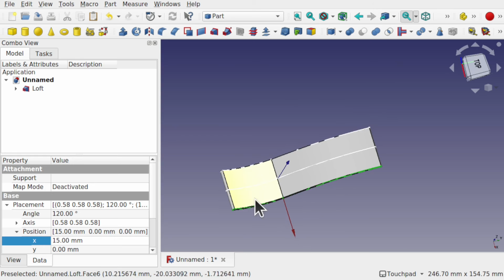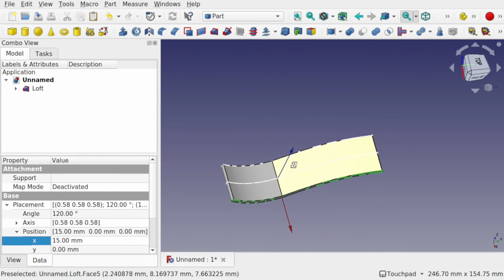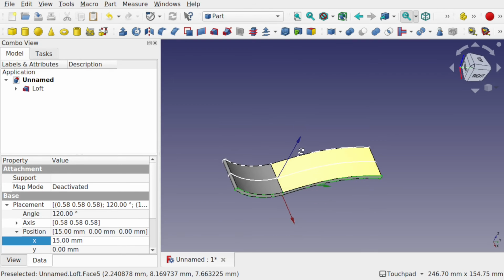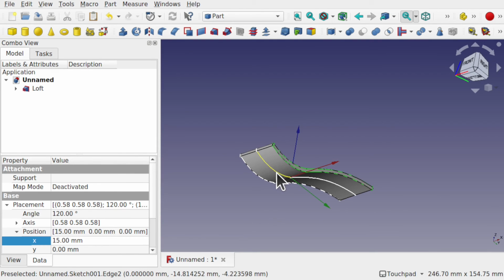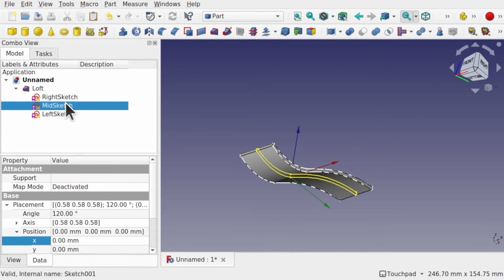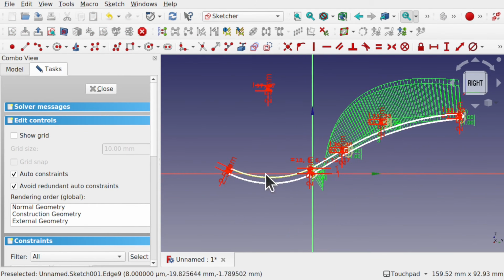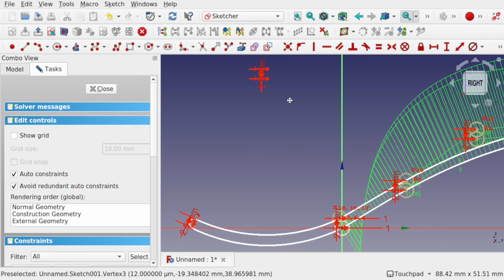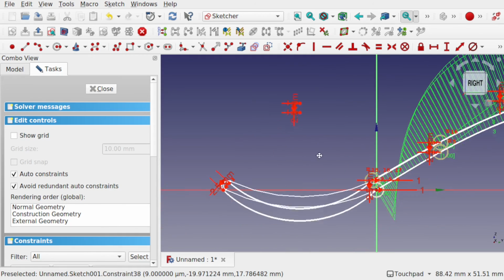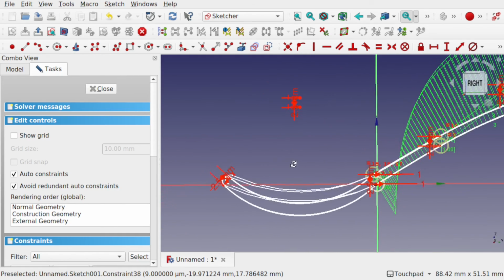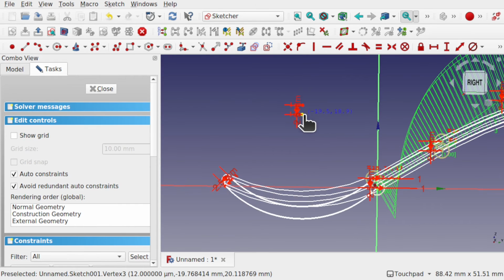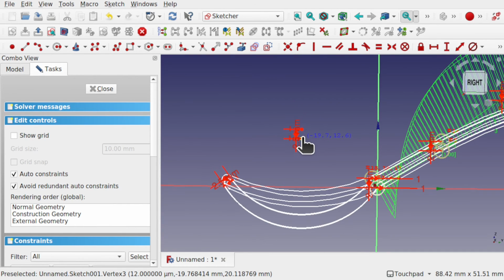And you can see what we're going to do. We're going to place the spoon shape upon here and do an intersection, but we need to deal with this center profile. Go into the loft and come down to the mid sketch and double click it. We've got that now. We need to curve this downwards. So I'm going to control that with the curvature here. And we can bring this down and you can see underneath it the other sketch is sitting there. And we can decide how far we want this to come down. So using your spoon as a reference, we can decide on that.